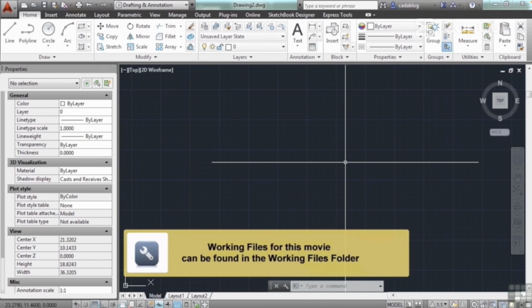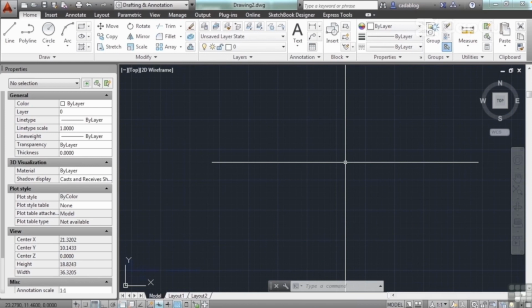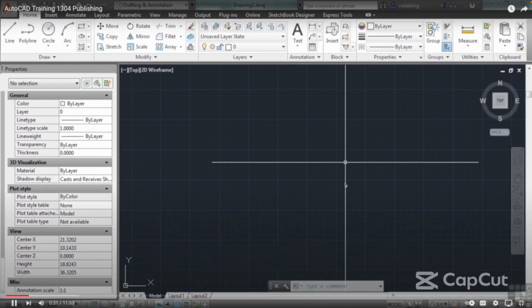Once they're set, we can do what's called a publish, and we can publish several drawings at once. It allows us to print more than one drawing at a time and multiple copies of it. The best part is that you don't even have to open up all the drawings, or any of them at all, really. There's a publish manager that you can use, and you can open it up while in any file and have it print any tab from any drawing, regardless if you've opened it up or not. This is why we use CAD.